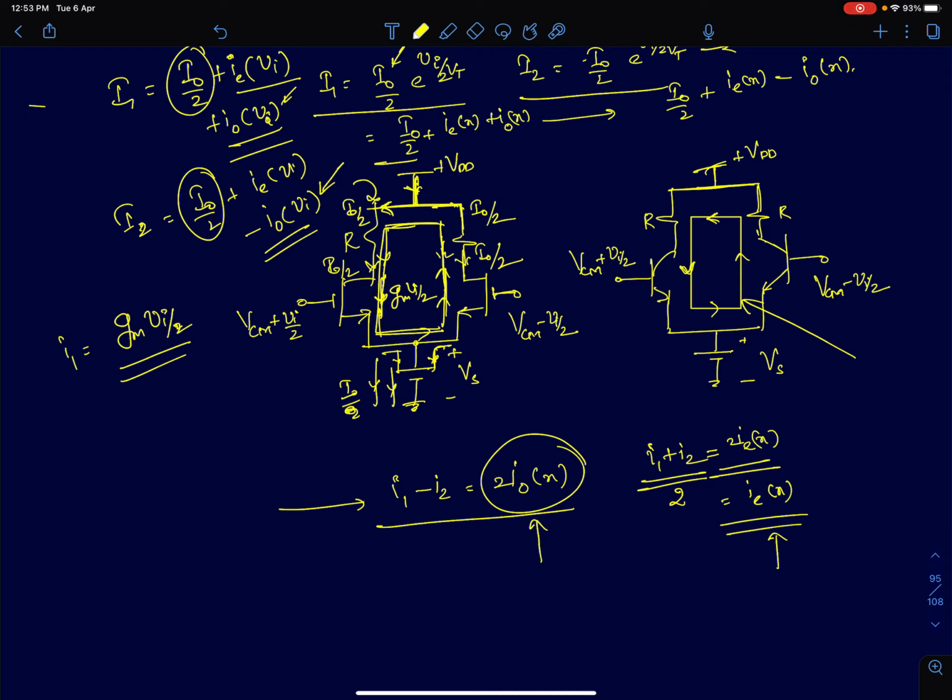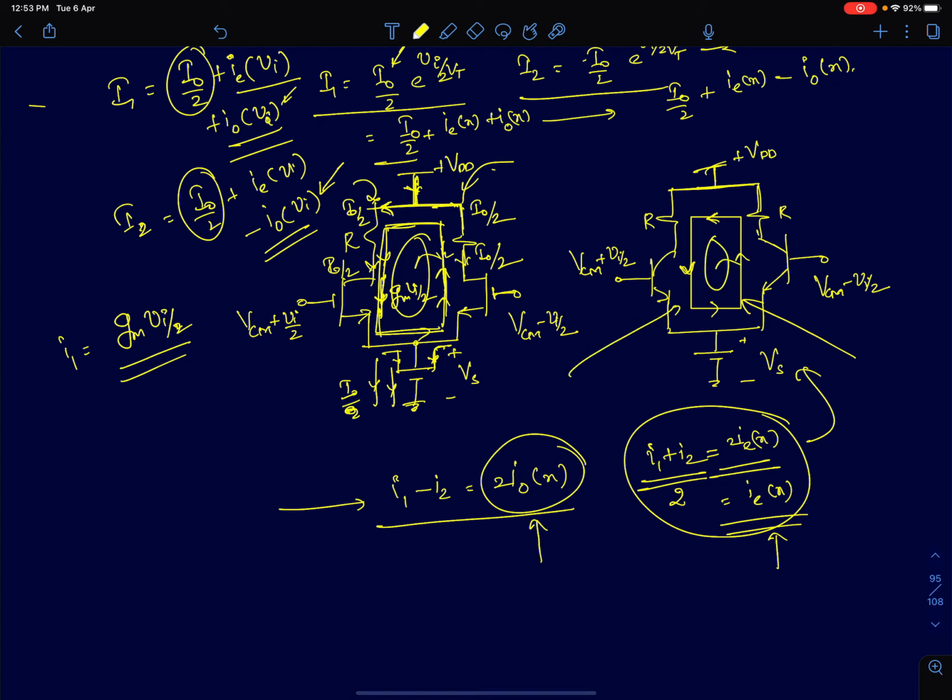And if you look at the common mode component I1 plus I2, in this circuit it contains only even harmonics. We also said what the path of those currents is. The supply is going to supply only even harmonics. Odd harmonics, on the other hand, will loop around this way, forming a loop as shown in the circuit.